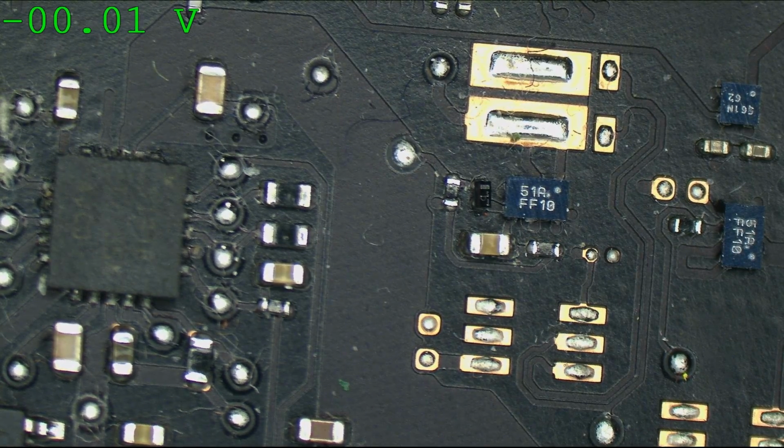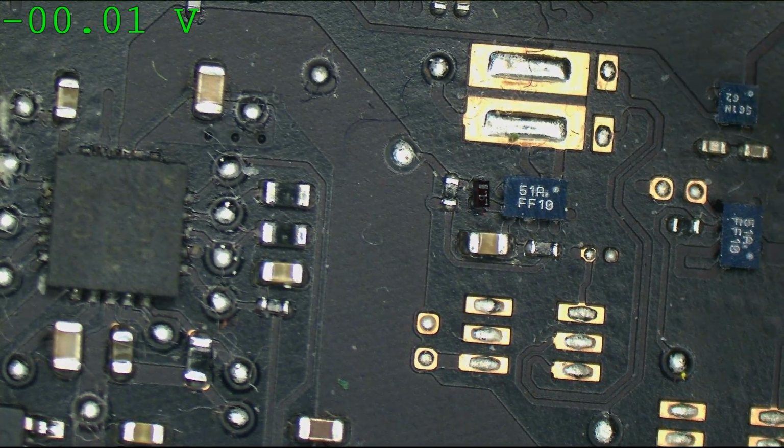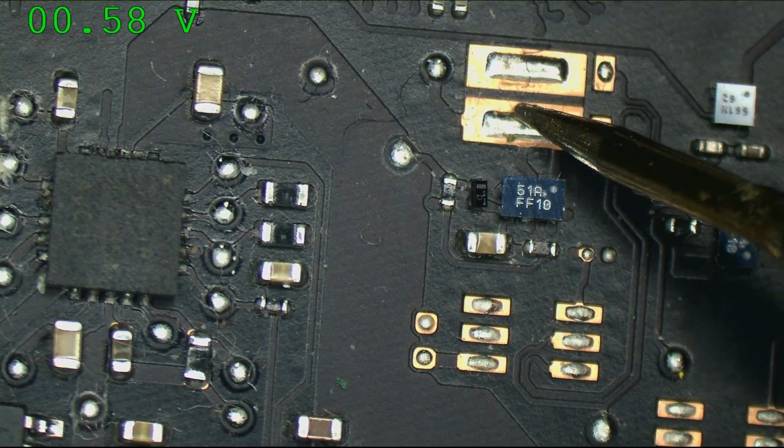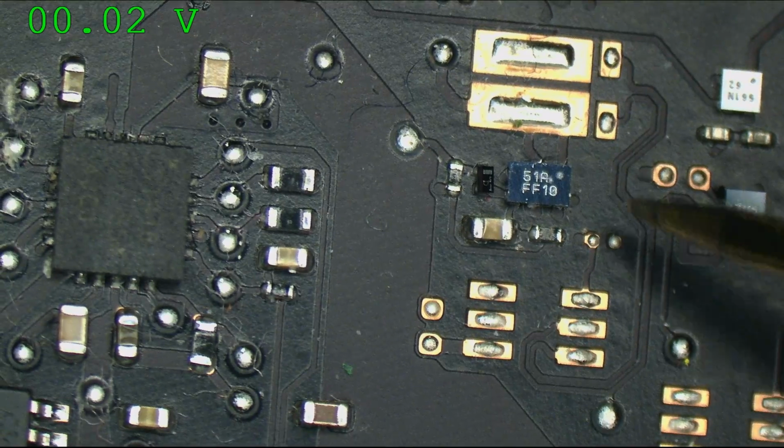Very interesting. Now, voltage out. PP3V3_S5 goes in, and then PP3V3_SO is supposed to come out, but it doesn't, which means that most likely our issue is with this little chip. Does it look bad at all?